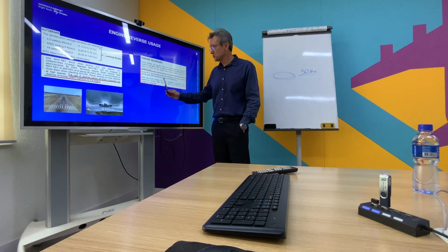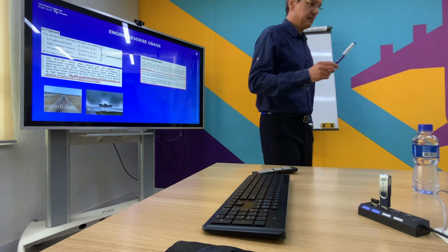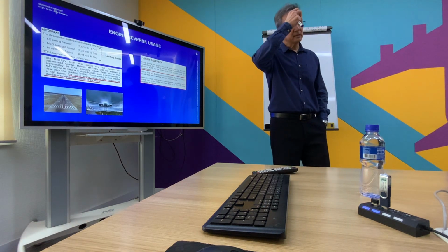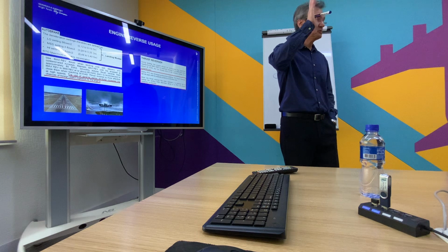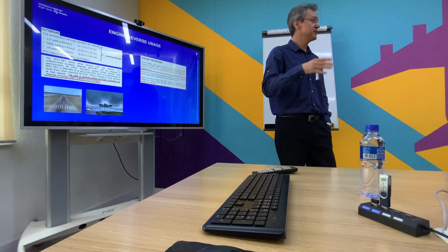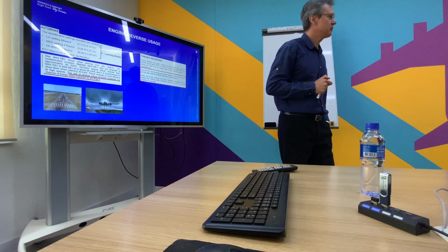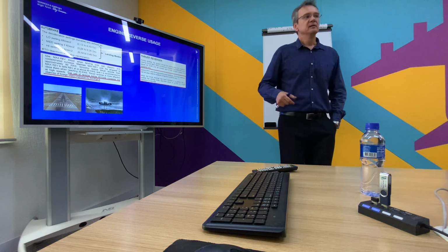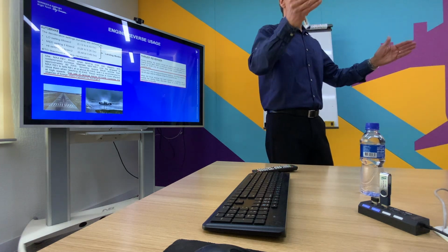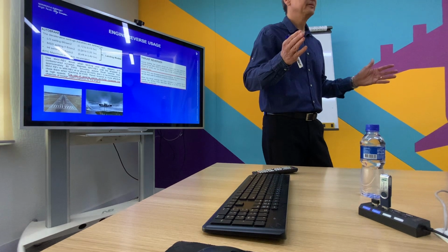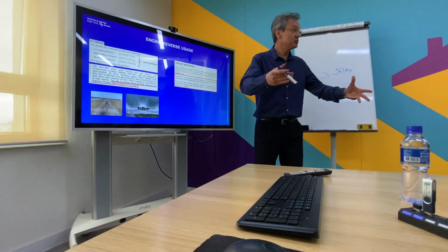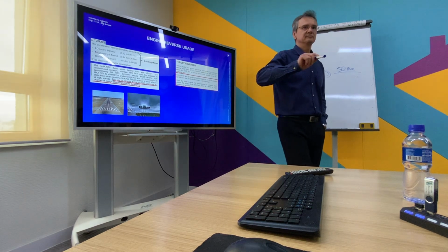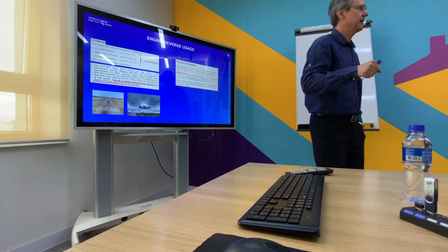And another good point to be discussed is, let's say a hypothetical situation: you are taking off and at around 120 knots, the tower says that the runway is blocked and you reject the takeoff. Okay? You reject the takeoff, auto braking max, and we are subject to startle effect, right? We are human beings, and we forget. Because of this rush situation, we forgot to stow the reverse. We went to a complete stop with reverse applied.